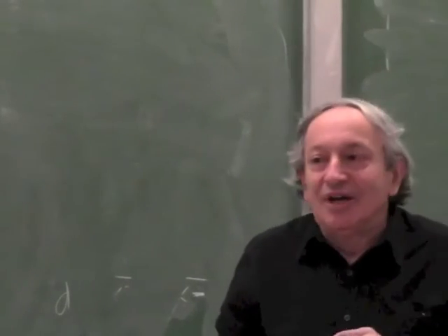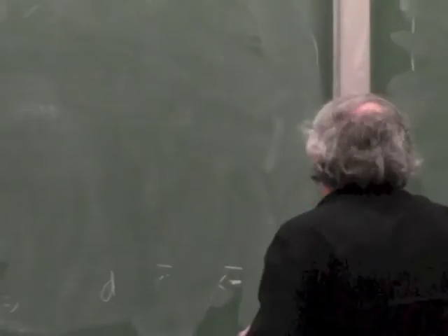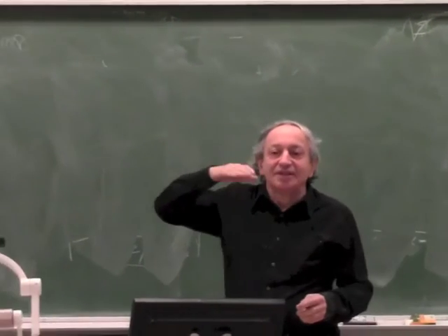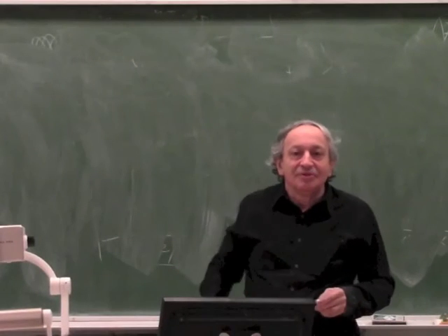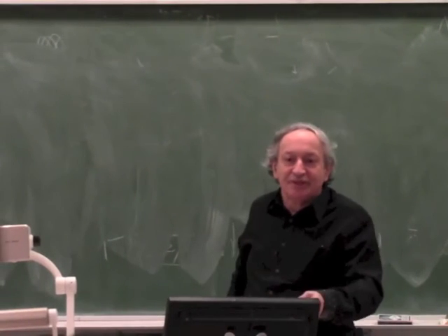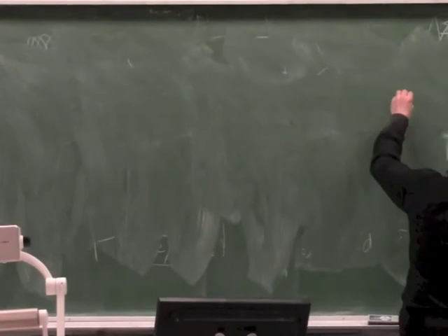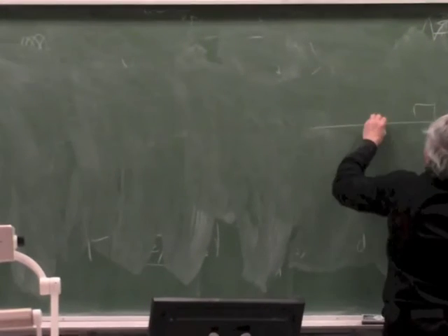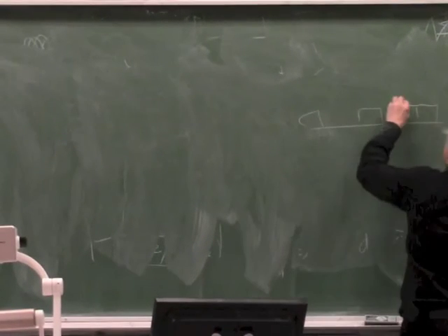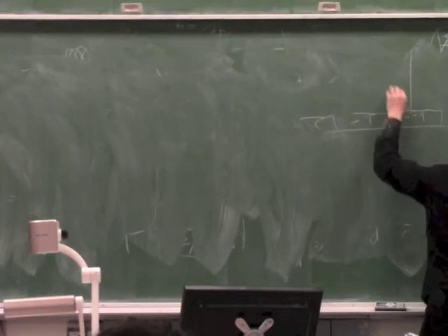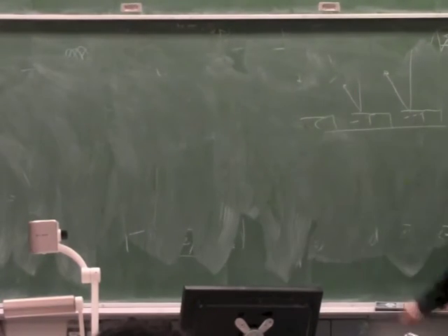Now, because of the snap, you cannot use it to modulate the light in a linear way. This was originally used for TV, and TV is analog, so each one of those mirrors, let's say the chip has 1 million mirrors, you wanted to tilt to modulate the reflected light.